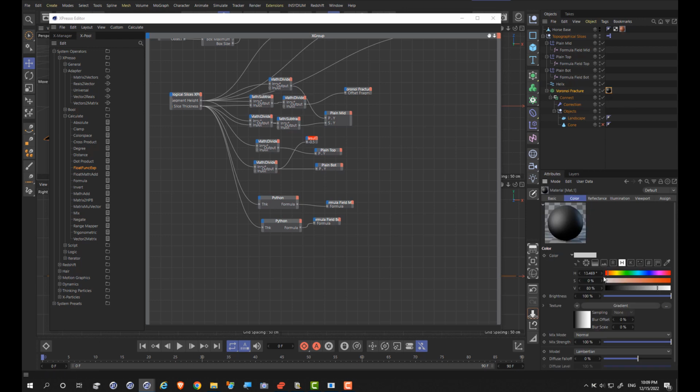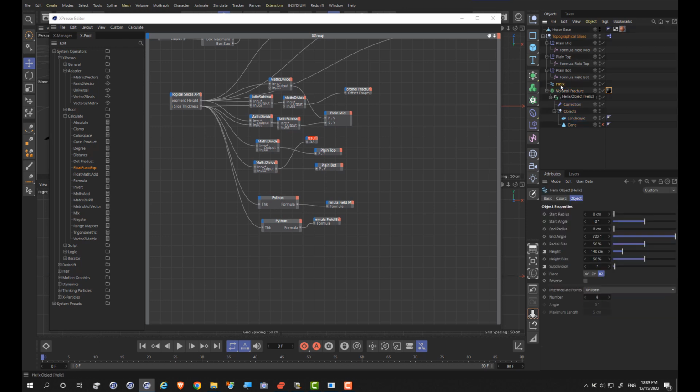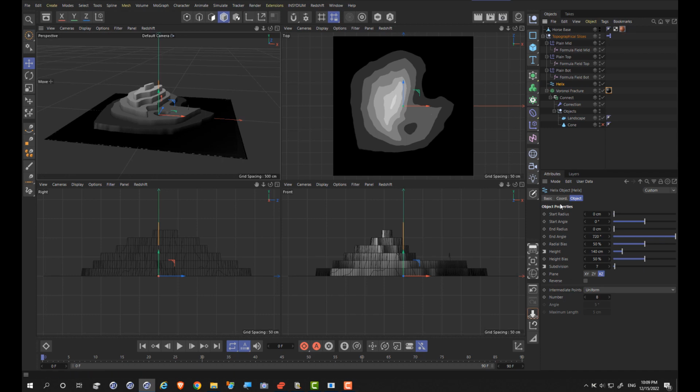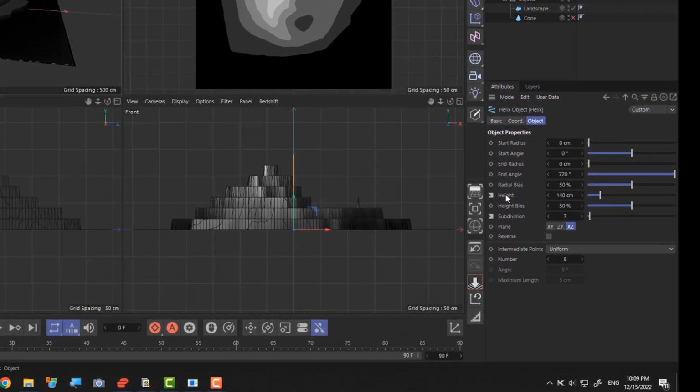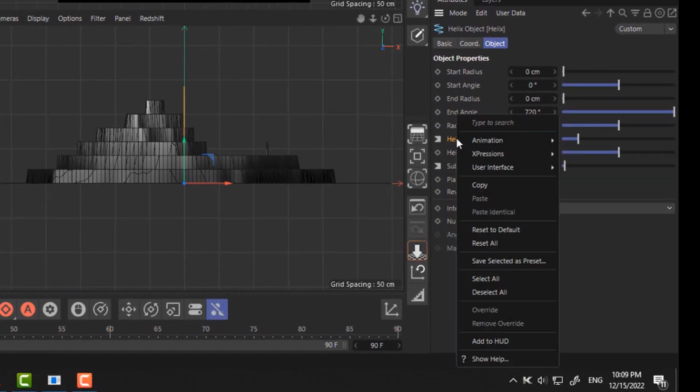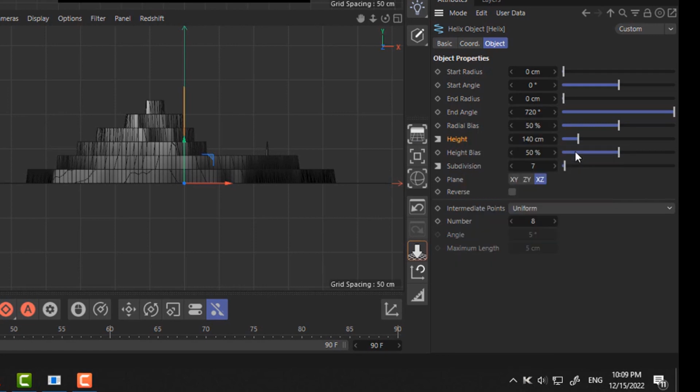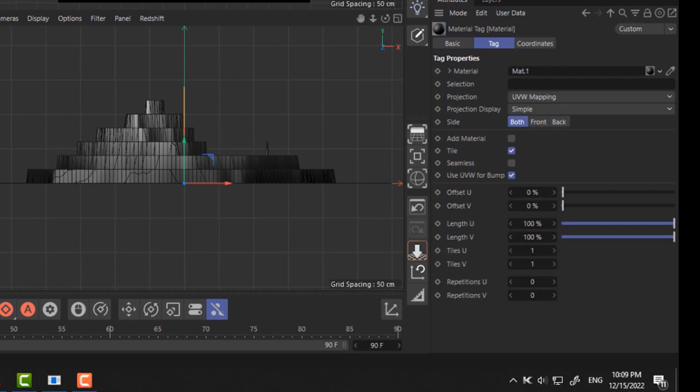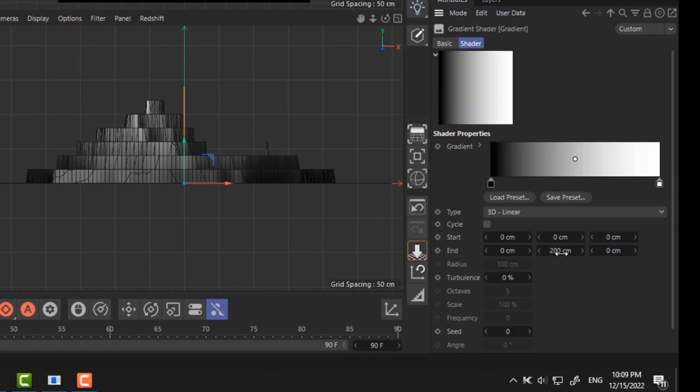Here's a hint. I'm going to make the helix, I'll close that for a second, the helix height a driver by doing expression set driver, and the color gradient Y driven. Well, it seems to be bundled into this vector here, and I can't set just the 200 unless I do this.